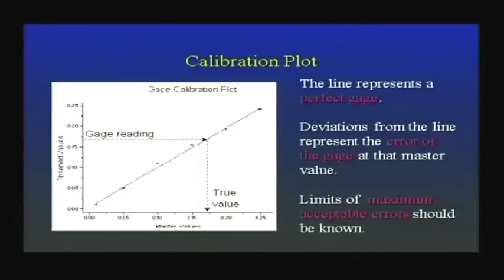Calibration, of course, is a way, like I mentioned, to make sure you have some idea of the inaccuracy in the system. Inaccuracy is the difference between your observed average and the true dimension. This is something that you'd like to eliminate. For this, periodically we take a gauge and get it calibrated. We submit it to a standards lab, and those standards people make the settings the way they are supposed to be, and they apply some standard voltage and look at the gauge at various settings. At various readings, they check with different amounts of voltage applied, and they take a look at the readings there.